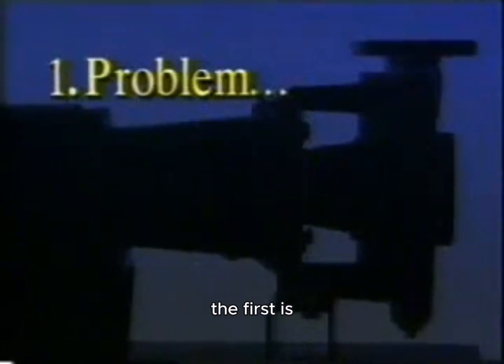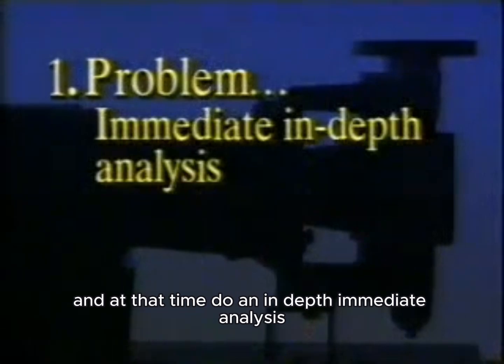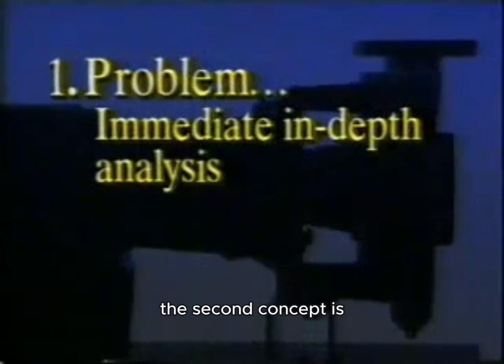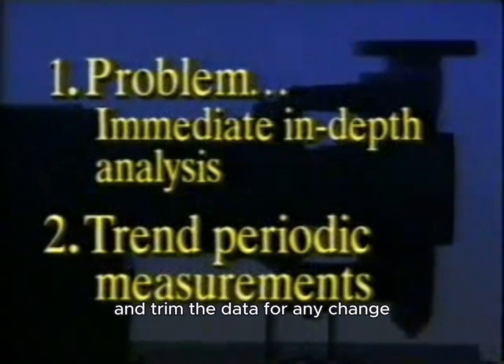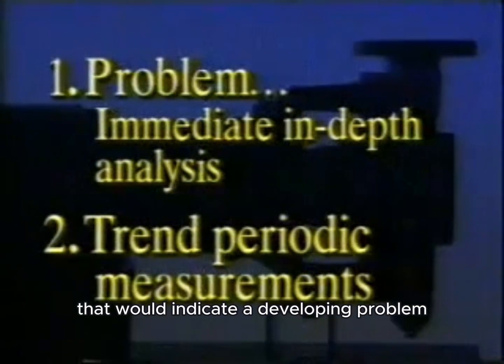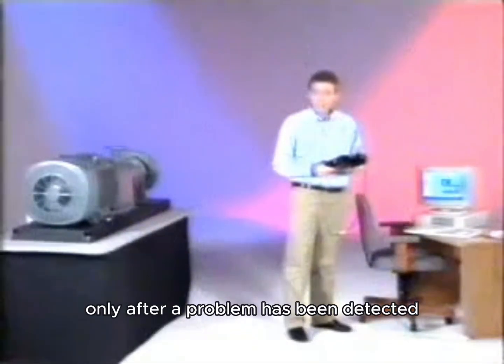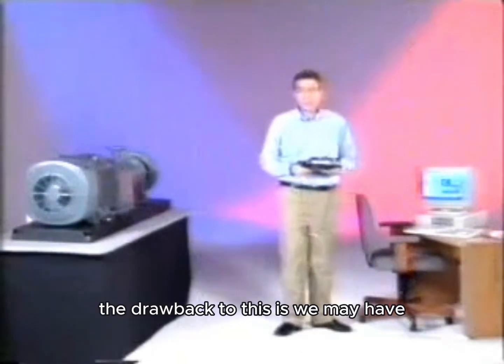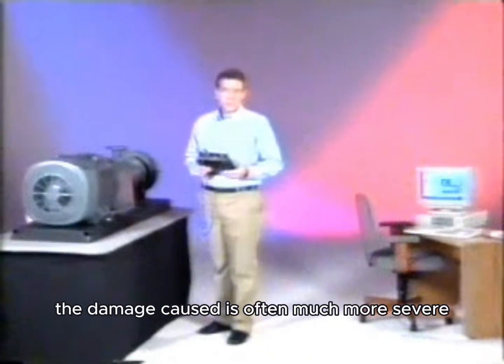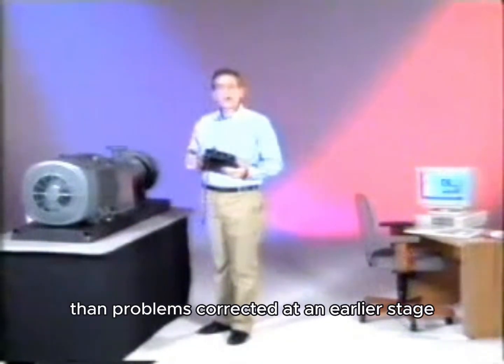There are two concepts for monitoring equipment like this. The first is, only collect data when a problem is suspected, and at that time do an in-depth immediate analysis. The second concept is, monitor the machine on a periodic basis and trend the data for any change that would indicate a developing problem. Analyzing a machine only after a problem has been detected seems to be a logical, labor-saving concept. The drawback to this is we may never know there is a problem until a failure is imminent or has already occurred. The damage caused is often much more severe and costly to repair than problems corrected at an earlier stage.